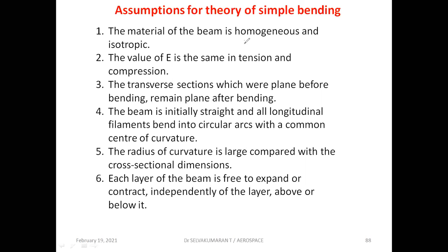So let me take, for example, this is my beam. We have the support here, and the support here. Now if you make a cut here and look from the side view, if it is a rectangular section, I'll get a rectangular shape. I can call this a transverse plane. When the beam is loaded, these transverse sections remain plane before and after bending. That's very, very important: before and after bending.